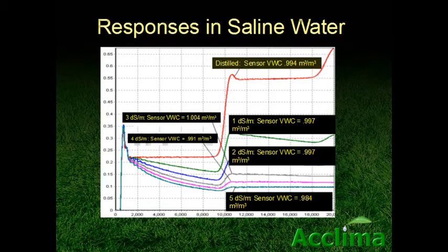These are actual, untouched, spontaneous waveforms and associated readings from the device in various saline water solutions. Note that the sensor reports fractional water content from 0 to 1, not as 0 to 1/2 as with most other sensors. Note the incident wave here at the left with its 100 picosecond rise time.